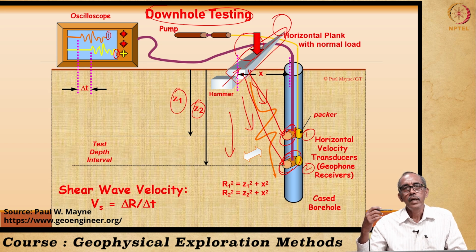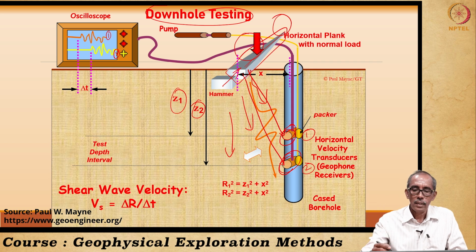And why do we go for downhole testing? Sometimes the information which we require may not be very critical, and hence we have drilled only one borehole to understand the velocity at different locations below the surface of the earth. Right.